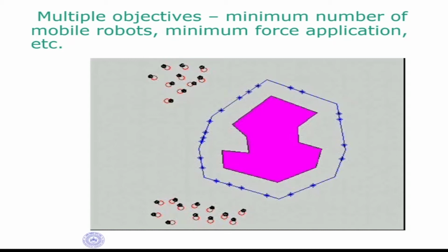So that is the objective of this path learning with multi-agents. Now this object is moving. If this robot tries to go and sit here, the object is going to hit the robot. So it doesn't go and sit on the object straight away. It has an expanded boundary like this, on which the robot goes and sits. That is what we are seeing here.